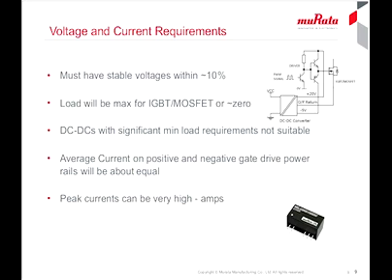It's important that these voltages are kept within about 10% and that they are accurate at the calculated load. In fact, the load on the DC-DC is constant and does not depend on the PWM duty cycle because the gate capacitance is charged and discharged every cycle, whatever the duty cycle. So the total energy and average current is the same.